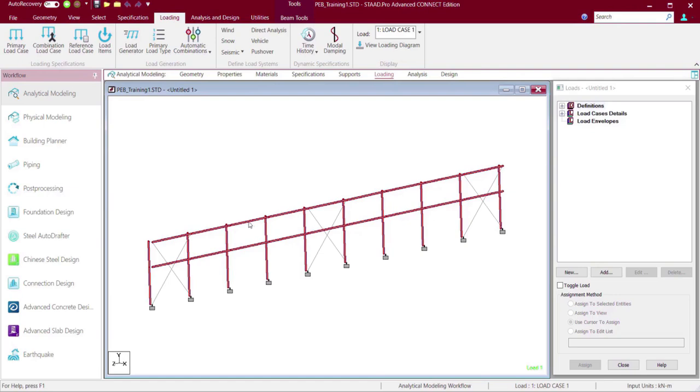But before that, you need to define this influence area, right? Okay, now here we are subdividing into different groups to define those vertical panels where the wind load is supposed to hit. Please remember, don't get confused with the floor load. Floor load is basically for the dead load, gravity load, but here we are defining the wind load. The procedure is different, but there is some similarity.